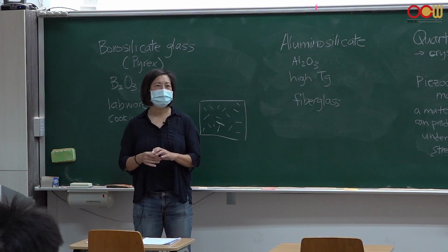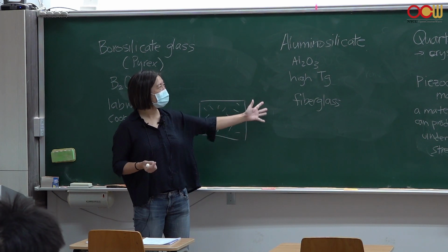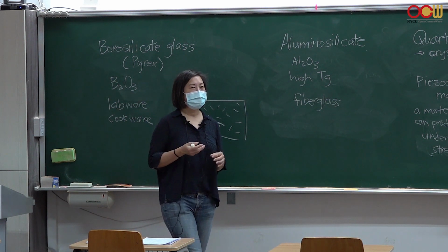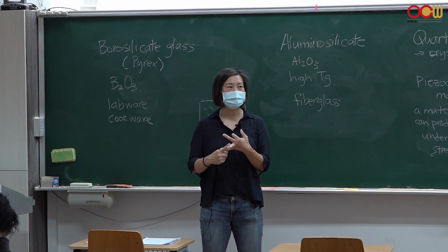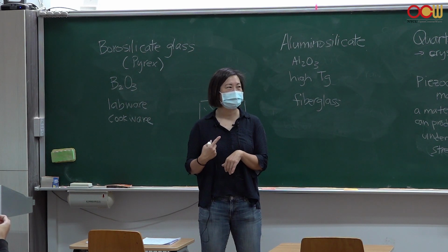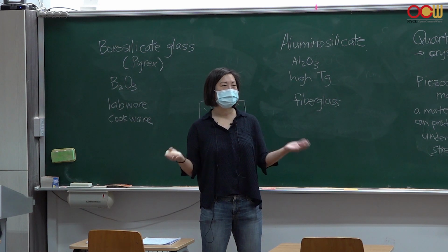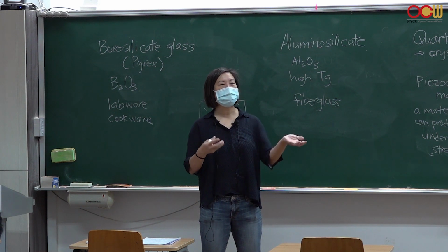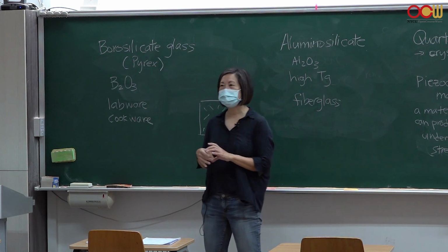Most of what you're going to be using in that ceramic class is a lot of aluminum silicates. They're given different names. I don't know all the names in Chinese, but the content will have a lot of silica, SiO2, definitely alumina, and probably some magnesium, calcium, carbonate, and other things, depending on the color that you want to end up with, how hard you want the material to be, and at what temperature you're going to heat it, right? It depends on what you want that clay material to be.